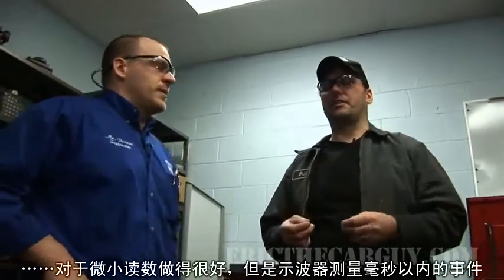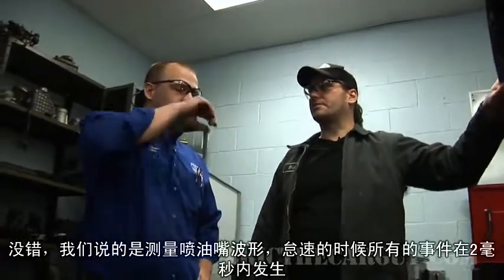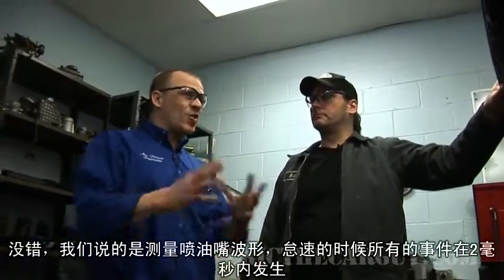Now let me ask you, if we don't have a fancy lab scope, is this possible to do with maybe a DVOM? No, it's not quick enough. That's the difference between a lab scope and a DVOM. A DVOM is good for general readings, but lab scopes measure down to the millisecond. You need to watch those events down to those milliseconds. When we're looking at a fuel injector pattern where the whole event is 2 milliseconds long at idle, and I'm narrowing in on a fraction of that to see if this thing is moving or not, there's no chance you're going to pick it up with a multimeter. Okay, so we know that we can rule that out. Yeah.